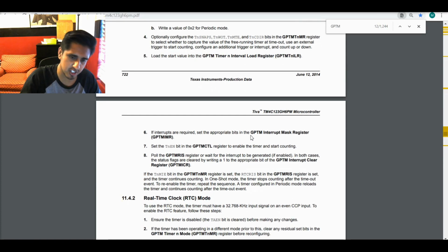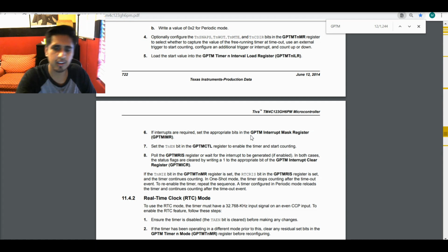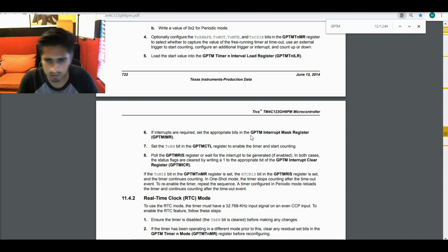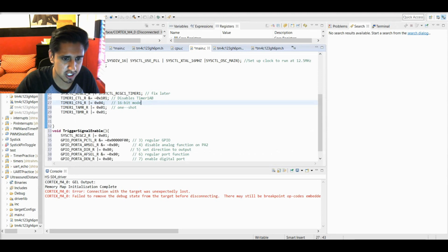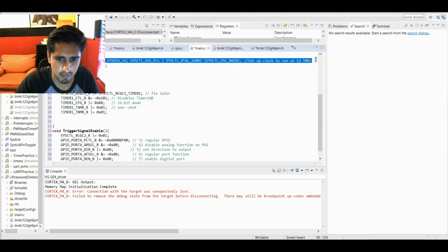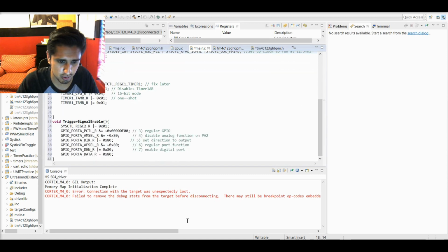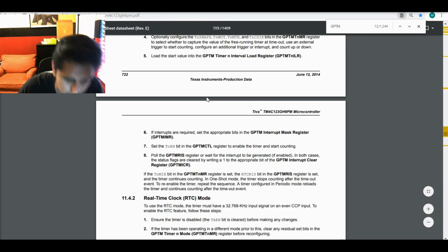It's going to start with all zeros, and then in the next clock cycle, the contents of the timer register are going to be 1, and then 2 and then 3, and each of these delta t's are equal to the processor clock. Which, by the way, I should have mentioned earlier, we set to 12.5 megahertz with this syscontrol. This is a driver function, so with the exception of these and other routines, we're not using any higher level abstraction support.